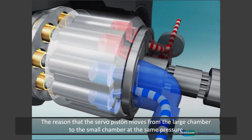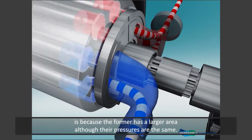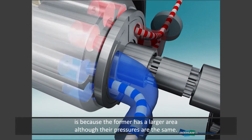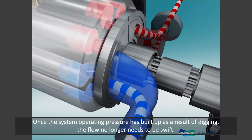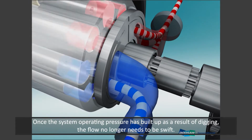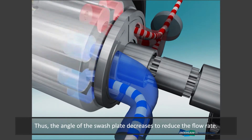The reason that the servo piston moves from the large chamber to the small chamber at the same pressure is because the former has a larger area, although their pressures are the same. Once the system operating pressure has built up as a result of digging, the flow no longer needs to be swift. Thus, the angle of the swash plate decreases to reduce the flow rate.